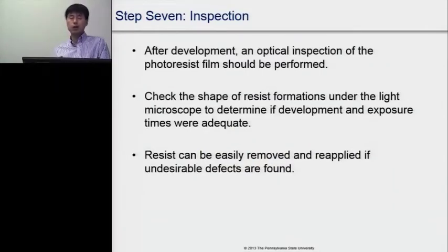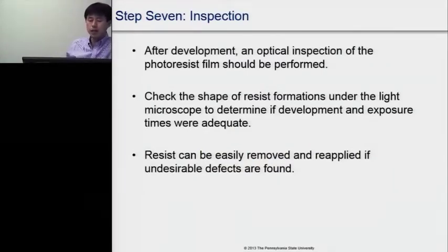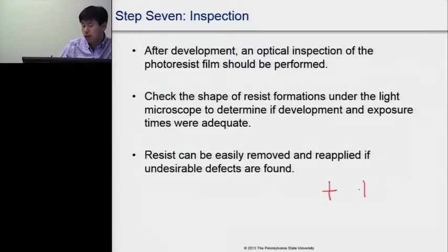After this, we rinse the substrate in DI water, dry it using a nitrogen gun, and then do the inspection. In this inspection, we check if the patterns are aligned very well. Alignment is one thing we are inspecting, and we also see if there are areas damaged during the process.